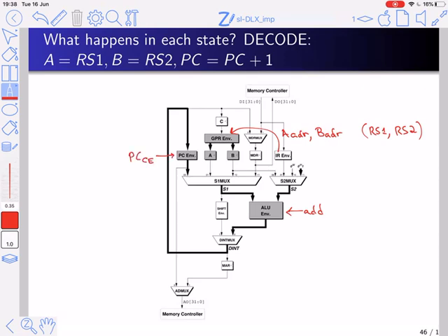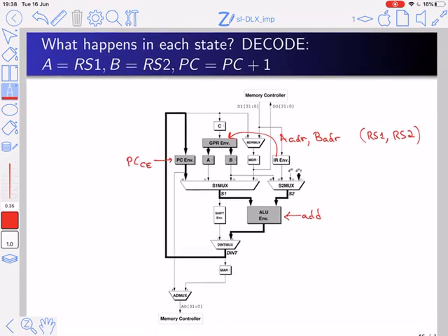And that's how the 3rd RTL instruction is executed during the decode stage. Notice that we could execute all of these RTLs concurrently because they used separate resources. Yeah, the GPR is a dual port RAM, so it can perform 2 reads in 1 clock cycle. This is the first 2 fellows.